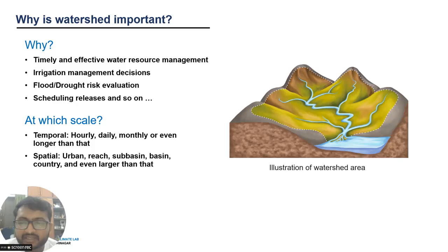This depends on what applications we are using it for. If we are interested in a flash flood study or urban floods, or the sudden downfall of a cloud burst, then hourly data is necessary. But if we are considering long-term floods and droughts, then daily data is necessary.